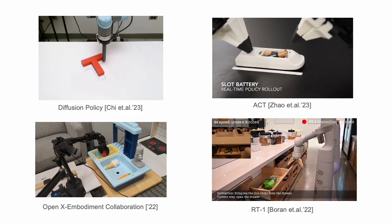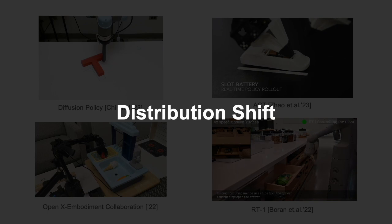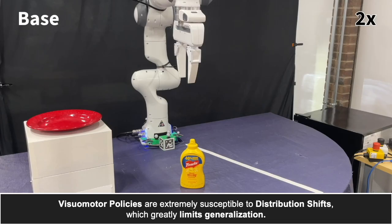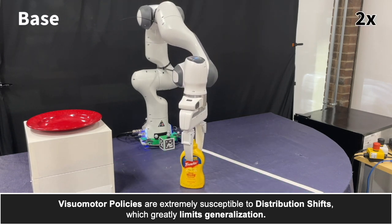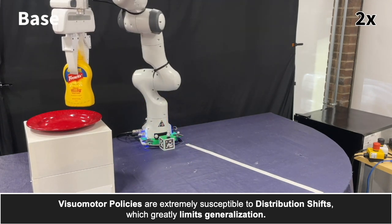However, current visuomotor policies suffer from distribution shifts, which can significantly limit their ability to generalize to unseen scenarios. For our running example, we present a well-trained, state-of-the-art visuomotor policy that has been trained exclusively with the object initialized on the green shaded regions of the table. In this setup, the policy performs as intended, lifting a bottle and placing it onto the red plate. We refer to this as our base policy.